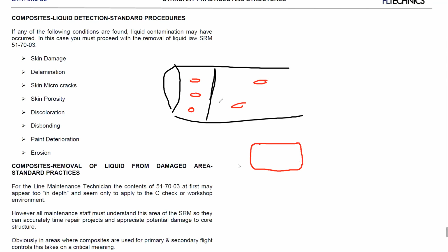Then there were audits from the authorities, and they found these very beautiful repairs. You can imagine the white color of the engine fan cowls and silver high-speed tapes in multiple places. They checked the logbooks, they checked the dent and buckle chart, or repair chart, whatever the name of the document is, and they found nothing about these repairs.